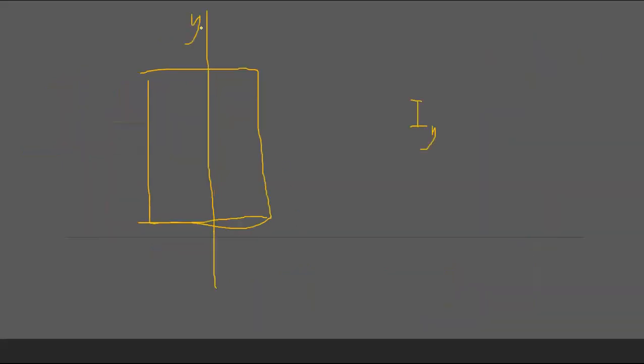So similarly, if you take y, so this is b, the same equation can be written, but now the intersecting axis length is b. So you have to interchange. So this is going to be db cubed over 12. Again, you have to check whether it is the centroid, right? This y-axis is going through the centroid. If and only if, you can use this equation.